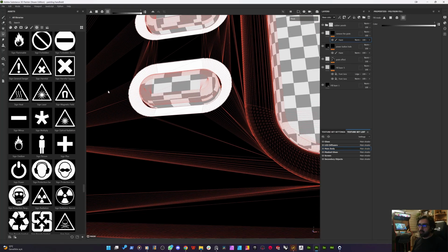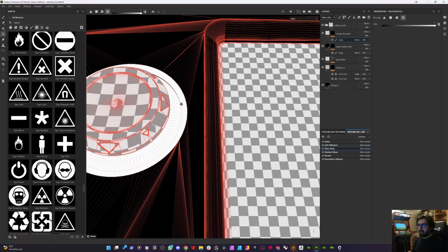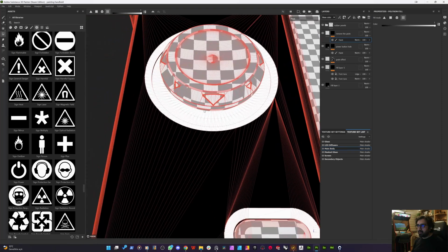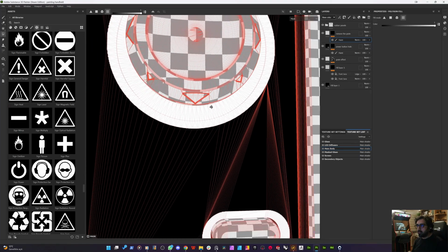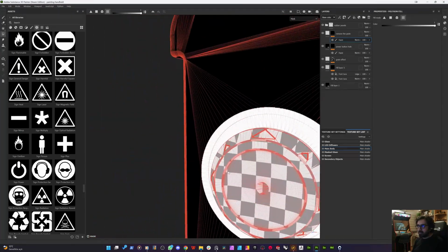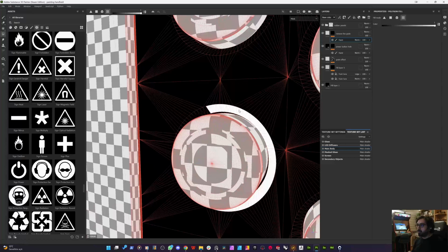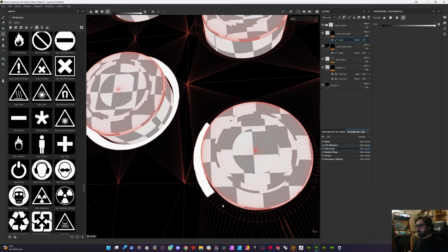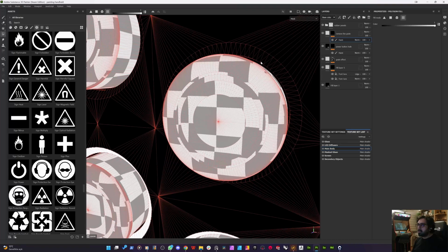Since I'm in UV chunk mode and I unwrapped the UVs in an automatic way, it just selects the areas UV island per UV island that were generated with a single part in the UV area. So that helps me easily select this kind of loops. So this workflow has some limitations, but also has some useful approaches inside.